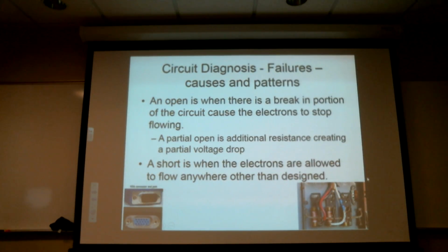So let's say I've got a relay being activated by a transistor driver, maybe it's a fuel pump relay in your car, being operated by a transistor driver in this computer in your car. And it's got 10% of the windings shorted. Current's going to go up, right? And because the current goes up, the magnetism is going to be probably about the same. So the relay is still going to work. Only the transistor is going to get hotter.